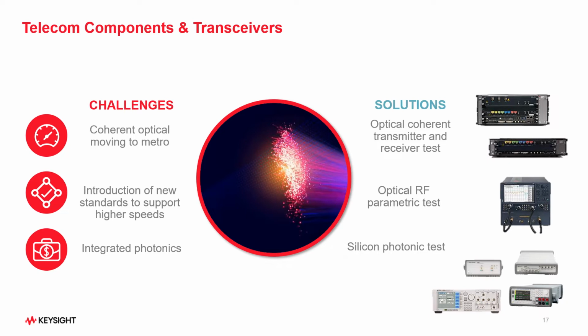The introduction of new standards will enable new generation technologies like optical coherent transmission technology, which was initially used in long haul transmission, and that would evolve into metro networks and expand into the data center. Significantly faster data transmission rates and greater levels of spectral efficiency can be achieved using higher order quadrature amplitude modulation, or QAM, signaling.